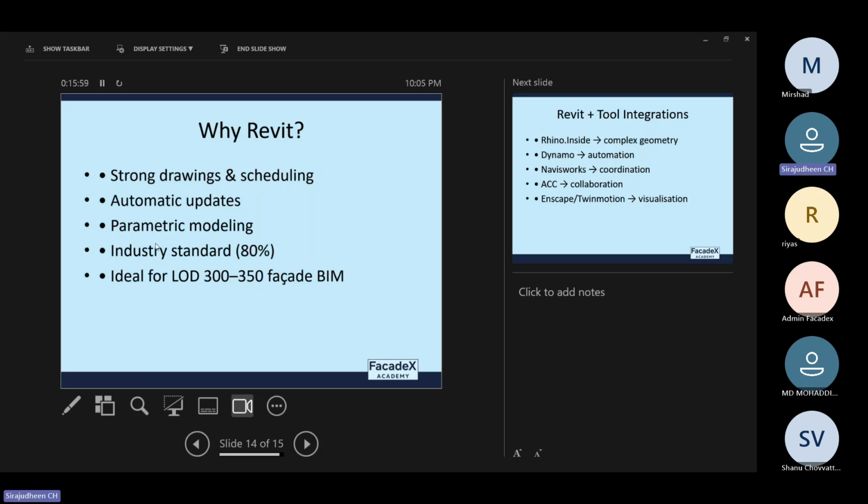And Revit supports parametric modeling. For example, if you are creating a door and the door comes in different sizes, we don't need to create different objects. We can make just one door parametric, so we can use it with varying sizes, like if the frame thickness is changing, or if the door width or door height is changing.